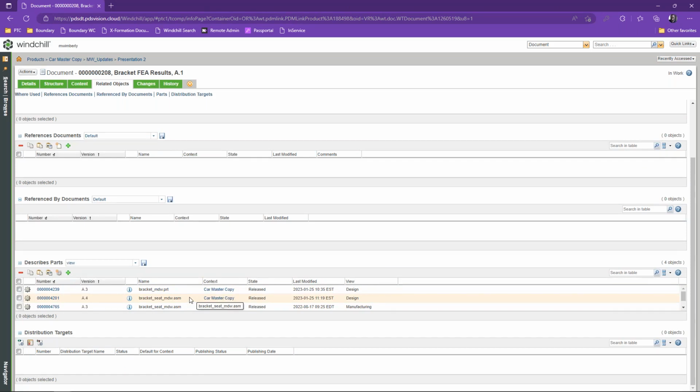WT part files are like your collectors inside of Windchill that we'll use for BOM structures, ERP integration, and change management, to designate the disposition of files that are changing, as well as to specify when something is expired. We can also set up effectivity dates on all those things inside of WT part files.